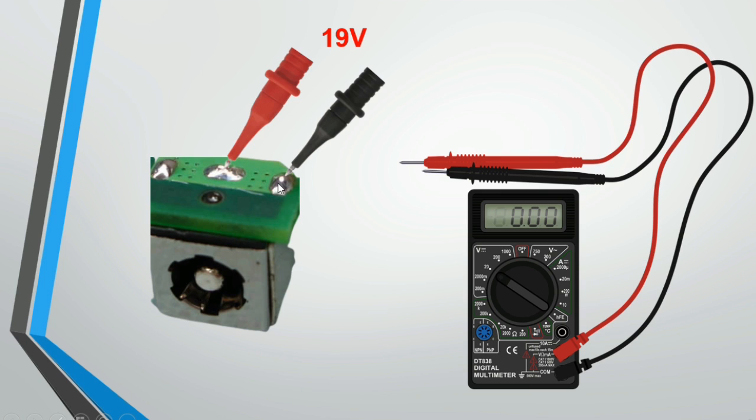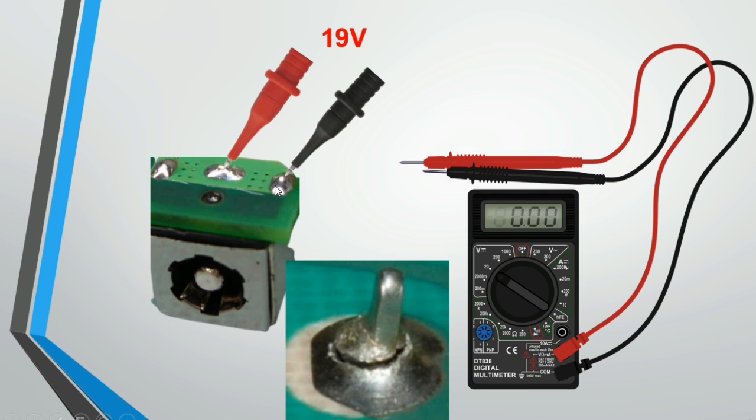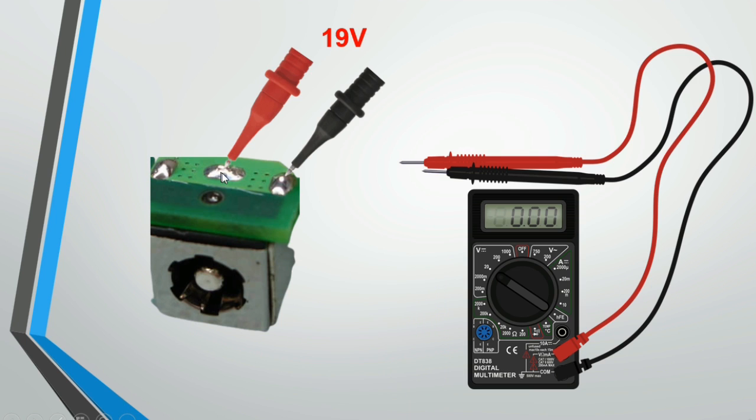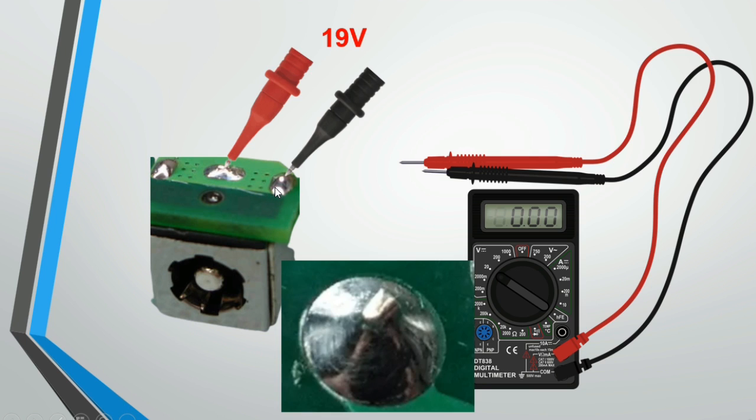You should first check that these pins are connected correctly to the motherboard. You should check that there is no dry joint or crack or something like that. Confirm that the pins are connected and soldered correctly to the motherboard.